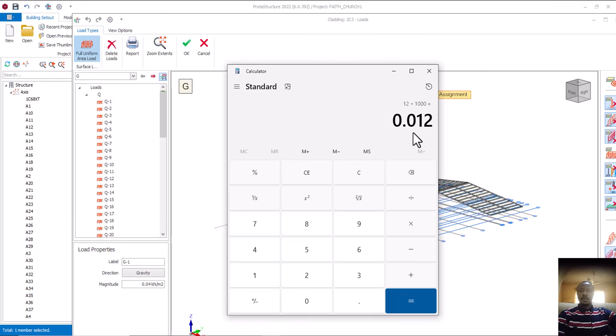Now, how do you know the density? The unit weight of gypsum is 8.5 kilonewton per meter cube. That's the unit weight of your gypsum board. Is that okay? So if you have this, multiply by your thickness of the board, which is 0.012. Am I correct? Yes. Equals to what? Can you see? So based on this, what I'm now having is 0.102 kilonewton per meter square. This is only for the weight of my board that I'm going to be using. So we keep it aside.